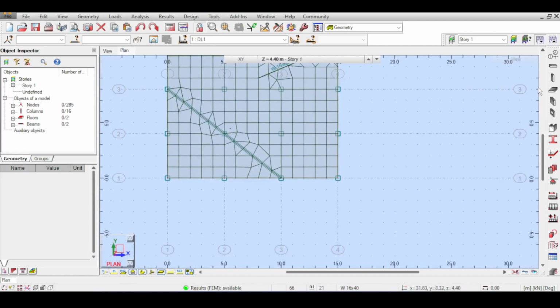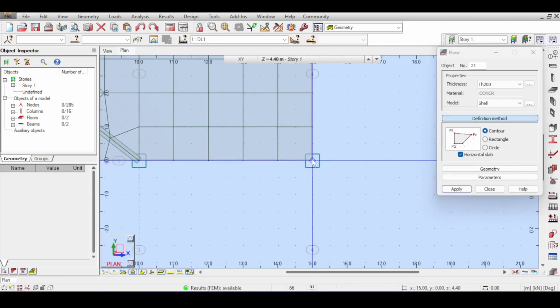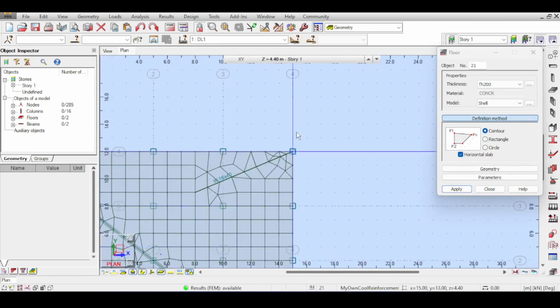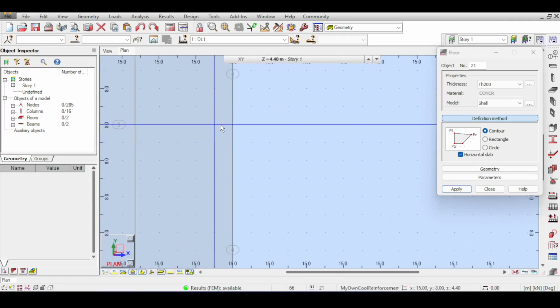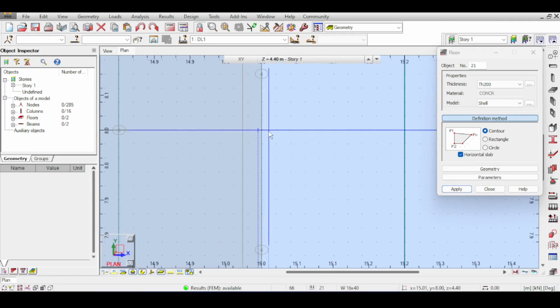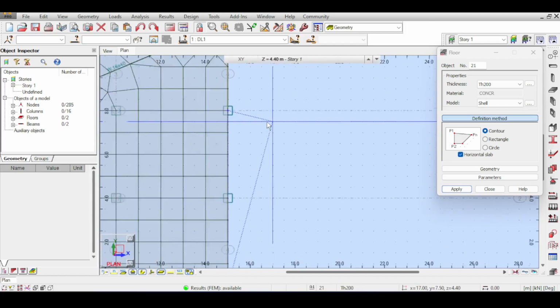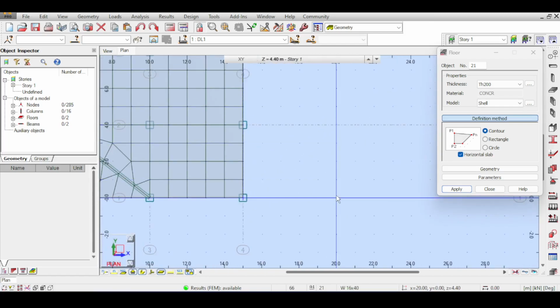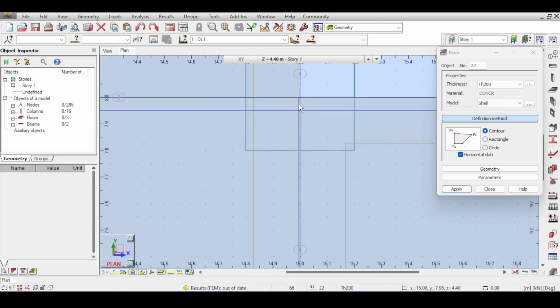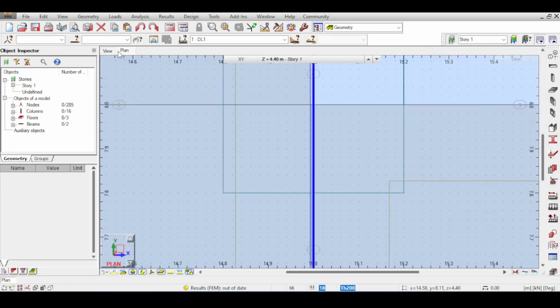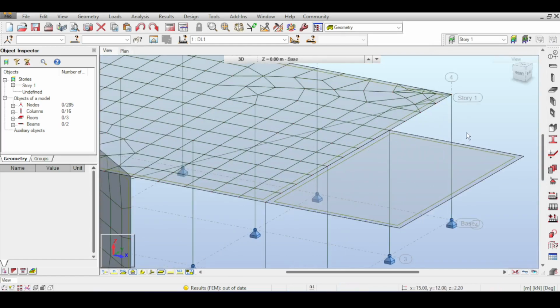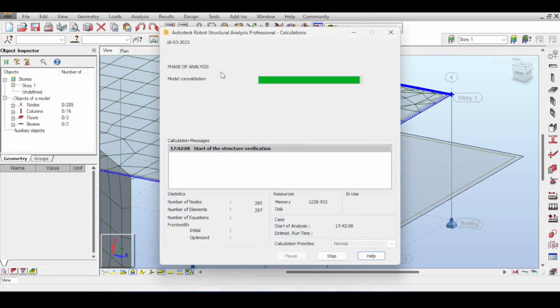Now, one of the mistakes one could make in a finite element analysis is to barely make a mistake in drawing and just do this. I'm drawing a plate here, but messing up something, as you can see. Now, this little detail here will cause all kinds of problems, at least in Robot when I was working in 2000. Robot 2010 didn't have the ability to mesh this. Let's check out if Robot 2017 does.